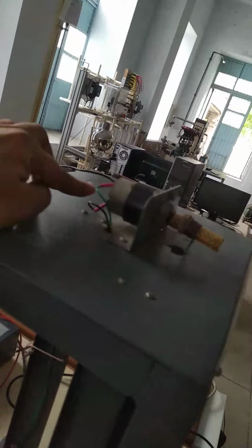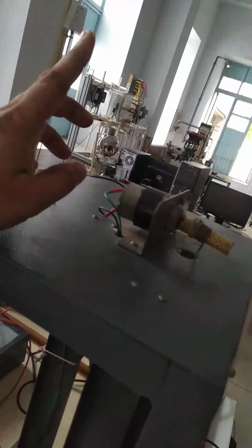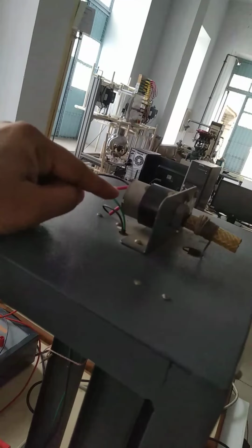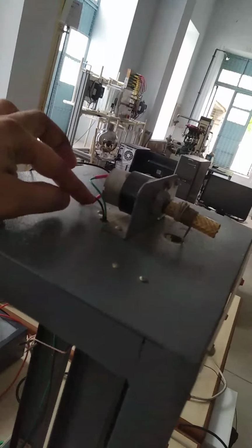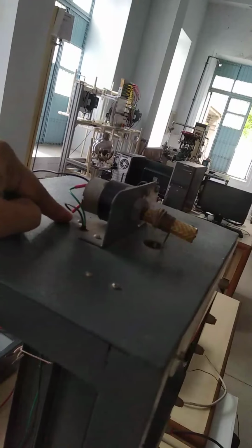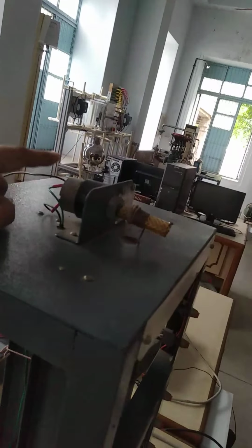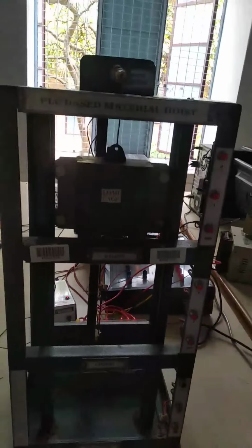Motor has two terminals, M1 and M2. The green color wire is M1, and the black color wire is connected to M2. If you apply M1 as positive and M2 as negative or ground, then the motor will move up. If you apply M2 as positive and M1 is made ground, then the motor will move down. So by changing the polarity of applied voltage, it is possible to make the load cage move up and down.